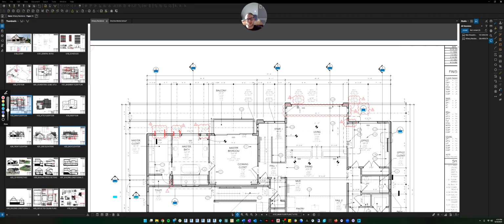But in residential construction, in a framed wall, they like to dimension to the middle of the window or the opening. So if it was a door, you'd also dimension to the middle of the door. So that's what I've done. It's not important for this class which one you do. You just need to pick one and be consistent. That's the most important thing. If you want to do the edge of the windows, you can. But just don't do the edge of the windows on one wall, but then on the next wall you do centers. That's not correct. That's always wrong. So pick one or the other and stay consistent.